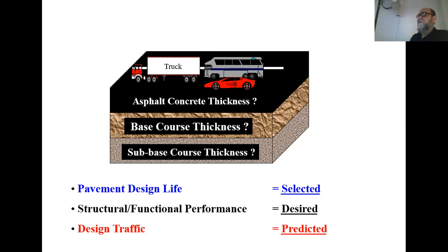Before I move ahead, there is a simple thumb rule that you must remember. We don't design pavement for cars. We design pavement for trucks, mini trucks, or in other words, any vehicle that has more than 4 wheels, or at least 6 wheels. So if you come up with, say, some high-roof van that has 4 tires and can carry, say, 16 or 17 people, even there we don't consider it for the pavement thickness.